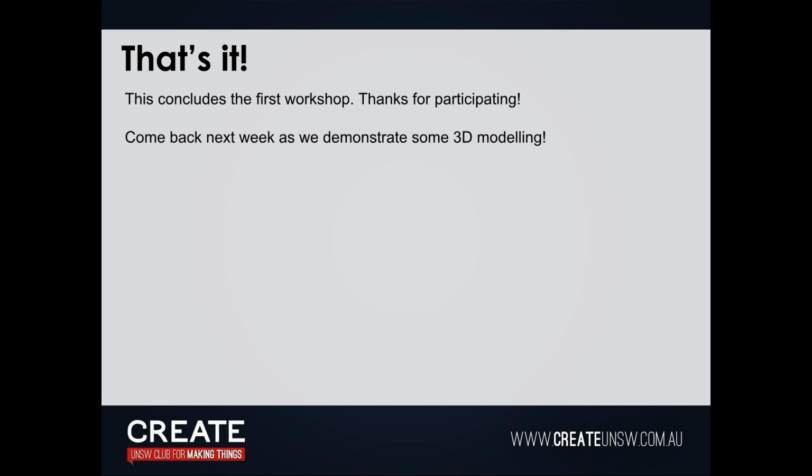There's a tool called split. Where's split body? Here we go. It's a modifier. It's called split body. So body to split. This is the body. Splitting tool is the plane. That's what you do. Now you've selected the splitting tool. Hit OK. Now they're actually split in 2.